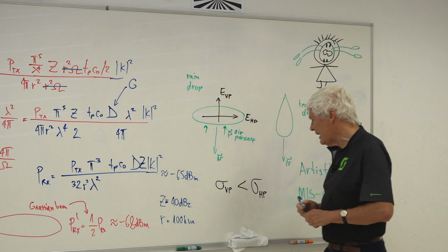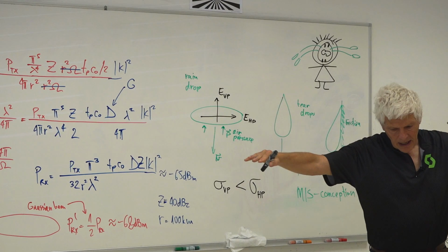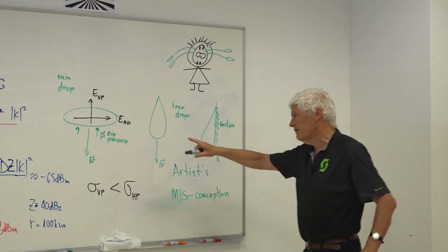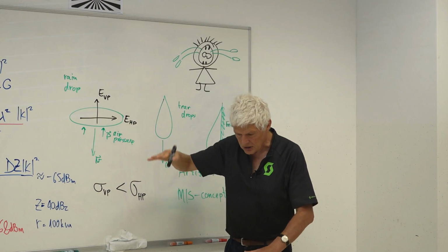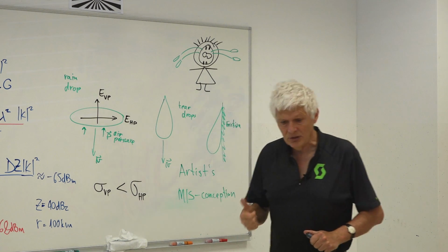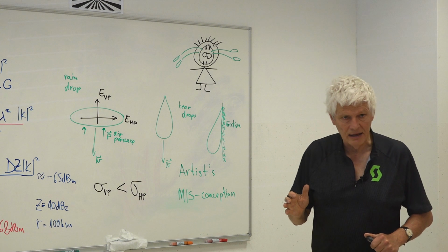The effect is larger for horizontal polarization because raindrops actually have a larger size in the horizontal plane rather than in the vertical plane, because raindrops are flattened, due to air pressure slowing their movement down there. You can actually see this with your own eyes with just another physical example.